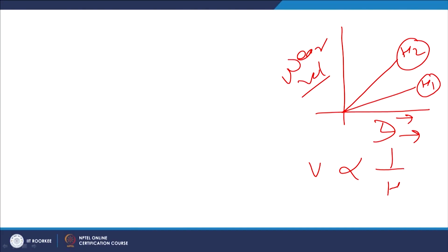Now, this was Archard's law, but most of the time we do not see that the variation is that linear for the hardness. It means the wear volume is not always exactly inversely proportional to the hardness. Sometimes we may have different kinds of trends in the variation of wear volume as a function of hardness. So, this law not necessarily will be followed under all situations, but this is a classical and original law which was derived to understand how different materials will behave if they have different hardnesses.